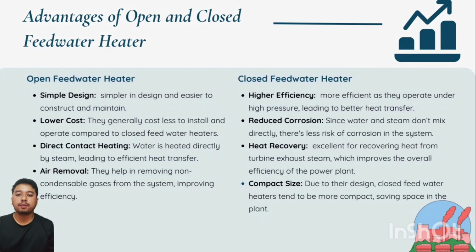Next, I will be explaining the advantages, disadvantages and application of both types of feed water heaters in power plants. Let's start with open feed water heaters. Here are some key advantages. For the first advantage, simple design. Open feed water heaters have a straightforward construction which makes them easier to design, build and maintain. This simplicity reduces the likelihood of mechanical issues and simplifies repair.